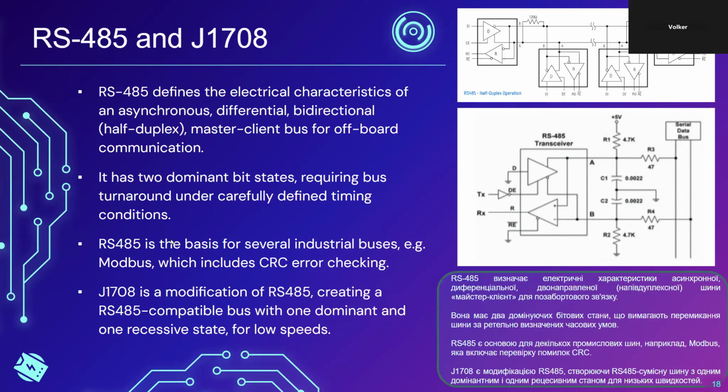If, for example, in cases where not a very high data speed is required, and when I'm saying not a very high data speed, I mean, for example, 19,200 bits per second, 19.2 kilobits per second, 38.4 kilobits per second. That is, of course, a fraction of what Ethernet can do. But Ethernet can go 100 meters, and then you have to switch to something different. RS-485 could run for kilometers.